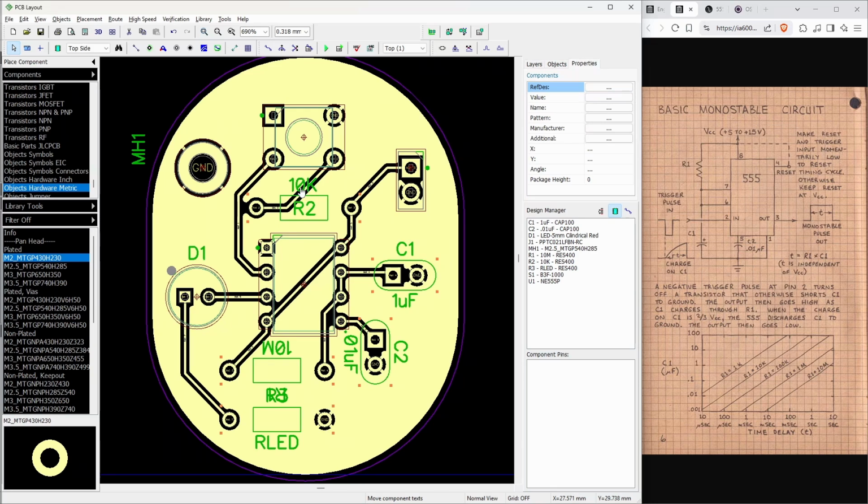It's okay to put Silkscreen over these gaps. It won't be noticeable on the finished thing. So, I think you could do that with the resistors, but then can I do that with the capacitor? It doesn't look like there's room. So I just have to decide what I want it to look like. And I think having the ref des and the value is handy.